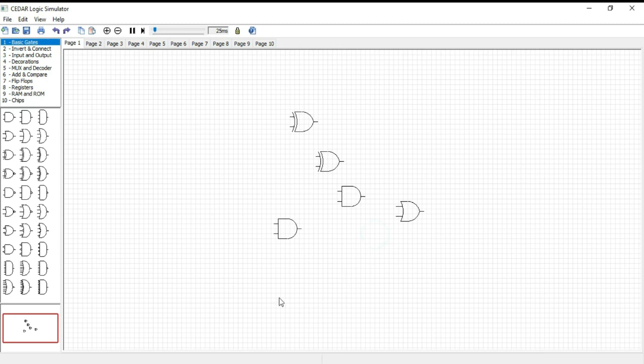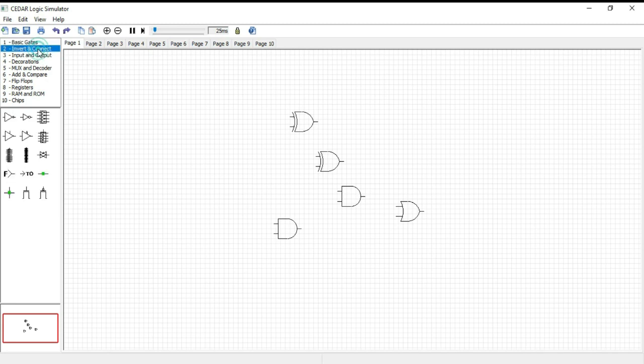Okay, now I'm going to add inputs by using from gates. So I go to input and connect and take from gates. It's a full adder, so I want three inputs. So I take three from gates. Okay. Now let's add our outputs by using two gates. So I take two gates for our outputs. Okay, let's construct this full adder by using wires.